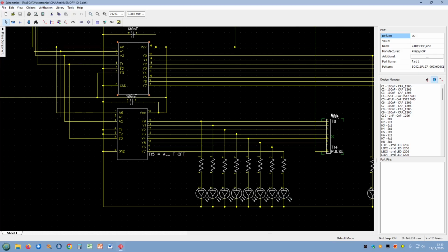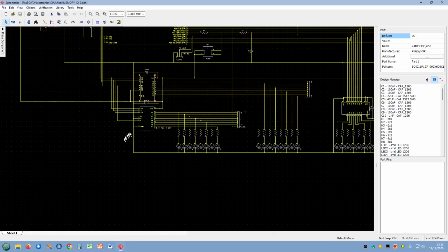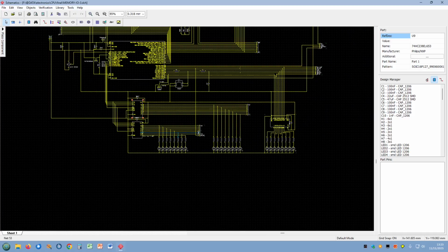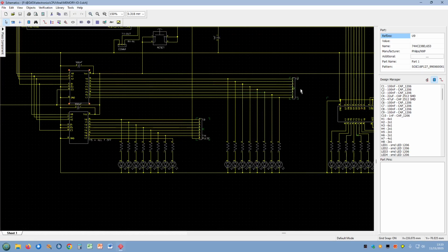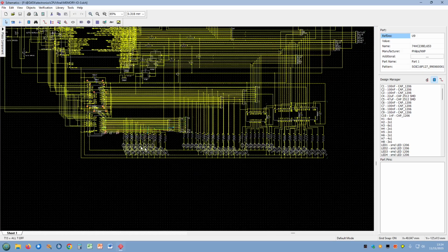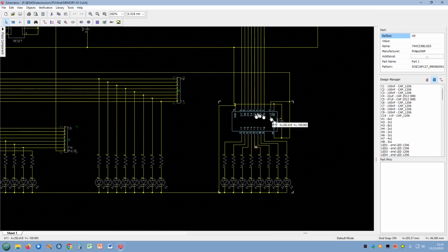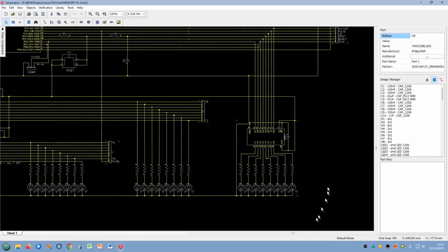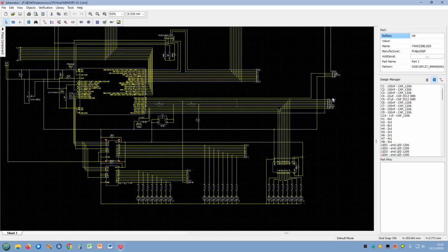And the spare slot going out here for the T-states, I actually brought the pulse signal and sent that out of there because that is actually needed on the instruction decoder. So there's one group there, and there's the other group there. There's all your T-states. And again, that's just another IC for lighting your LEDs.